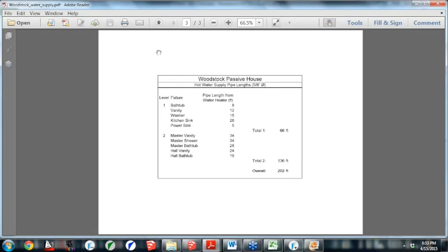Yeah, there's no difference between copper and PEX piping for hot water distribution. Maybe the exterior pipe dimension will be a little bit different. It's a little more complicated when you're using on-demand recirculation, but I would refer to the Phius certification guide for that. If you're using on-demand recirculation, you can use a reduction factor for the total length of individual pipes, but that's something a little too detailed for right now.